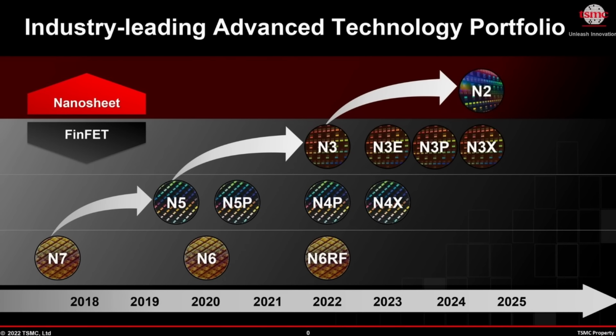So far we have covered 2 of the 3 basic concepts we need in order to understand what fin depopulation is and how FinFlex works. We know that current transistors are CMOS based, meaning they combine a NMOS and a PMOS transistor. And we know that these transistors are built as so-called FinFETs with elevated 3D structures. The higher the fins, the better the conductive performance of the transistor.